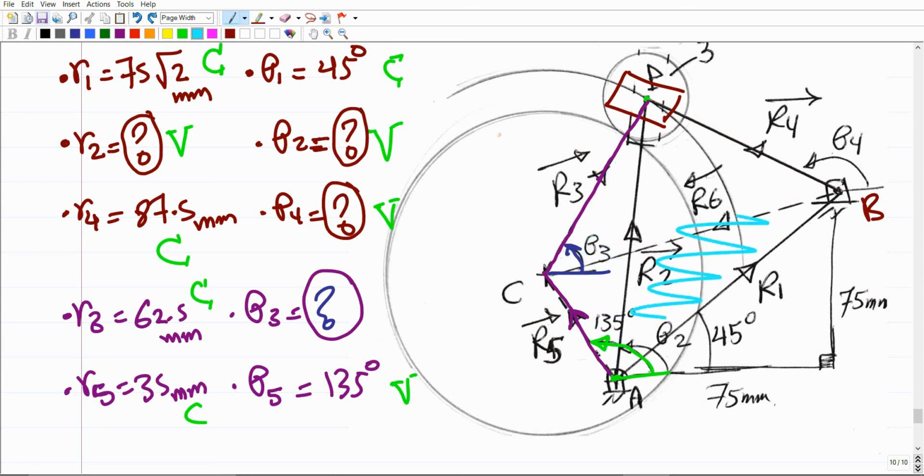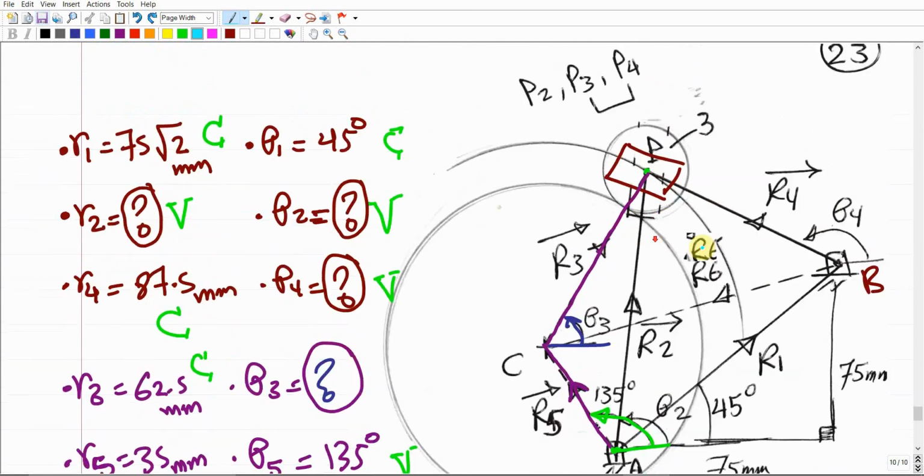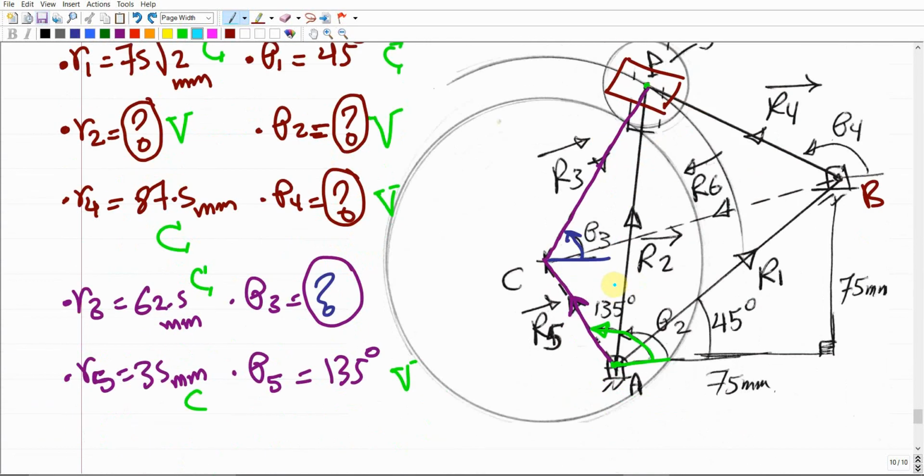So we're gonna be able to solve it. If we decided to pick the other loop on the left, we do have R1 fully defined, R4 has only 1 unknown, R2 has 2 unknowns. So as well, if we decided to work over the loop on the left, we're gonna end up with 3 unknowns. So we're gonna be able to proceed. So it is very clear that the problem is with R2, right? It means that I have to exclude R2 and we're gonna consider this big loop that includes R1, R5, R3, and R4 as one loop. Then I'm gonna solve this loop.